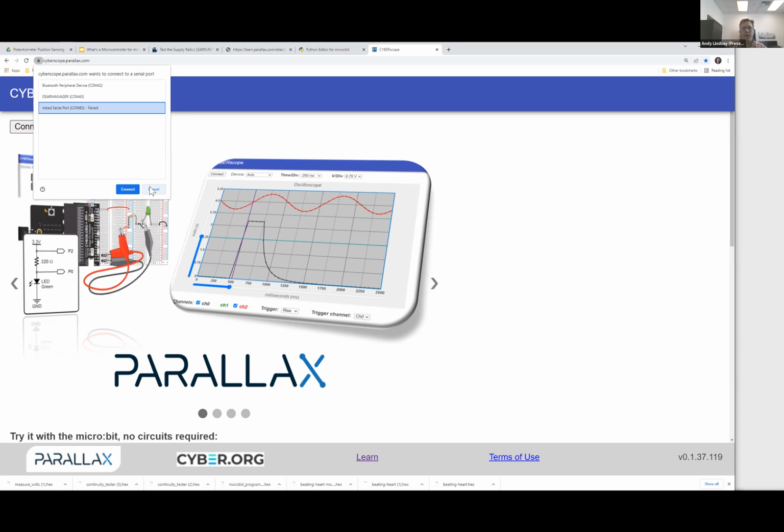Fantastic. So make sure to check a blue and a red socket in both the center and right columns, because we want to see 3 point something volts. And then if you put them in the same column, you want to see about 0 volts. And with that, you have a fully working system, and we'll start putting circuits on it.